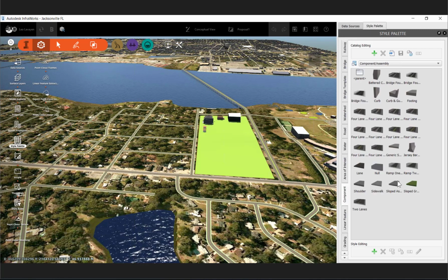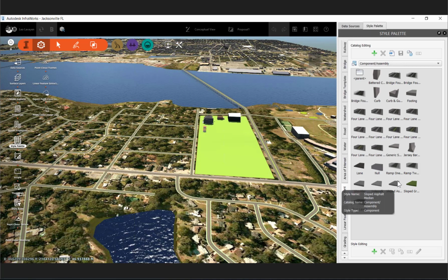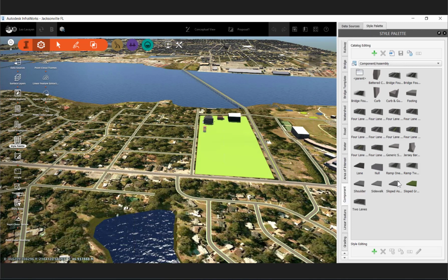The problem I would think about is very similar to how Civil 3D has a limitation with ditches. It's not going to allow you to design the ditch. It's going to be over at 2 to 1 for 5 feet, and then down 2 feet and up 2 feet, and that's what it's going to consistently cut all the way through. So in some places you're going to be carrying water, and some places it's going to be pooling water. So you are going to be able to put a typical cross section that represents a ditch, but you're not going to be able to design it per se. That's where we have to go to Civil 3D to take it to that level as of right now.